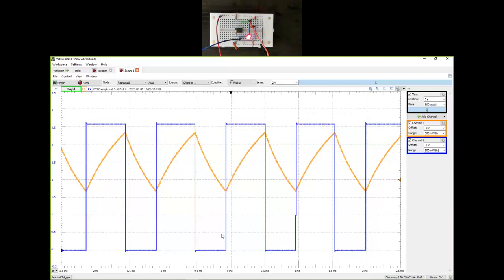However, based on the R1, R2 and C1 values that are used, we are not really able to enjoy the LED blinking. So in order to slow things down, we are going to have to play with the component values so we get a time period perhaps close to 1 second.